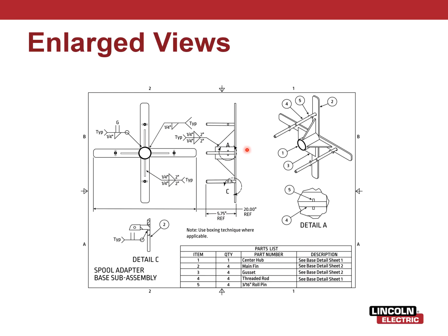If you come over to the multi-view drawing, front view, right view. They didn't need the top view, so they omitted it. So it's just front view and right view. If we look at detail A, we can tell this is the enlarged view. Over here, you've seen a couple small tabs, boom. And now you can have a better visual reference.